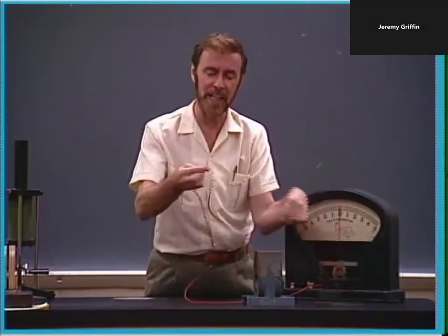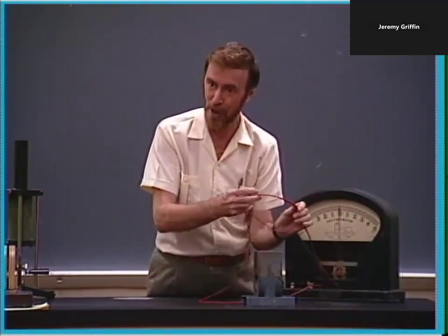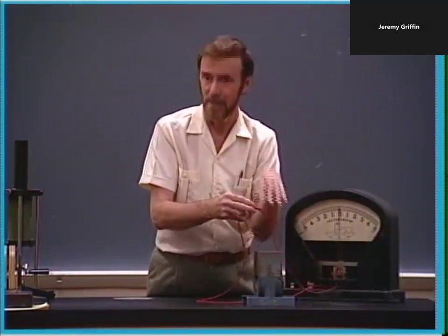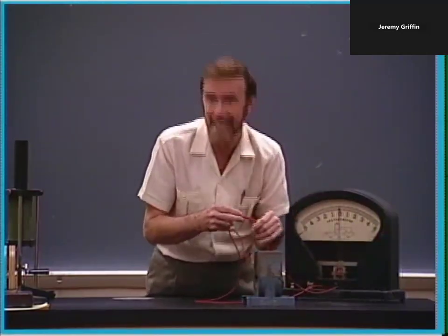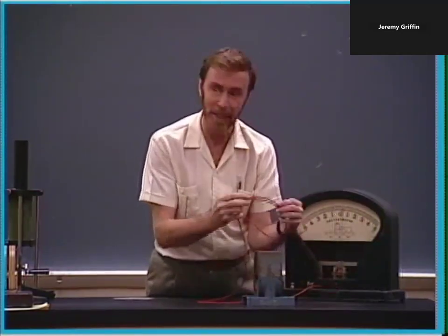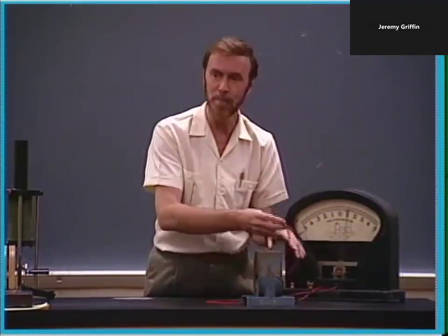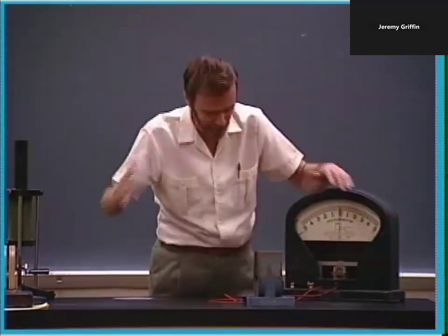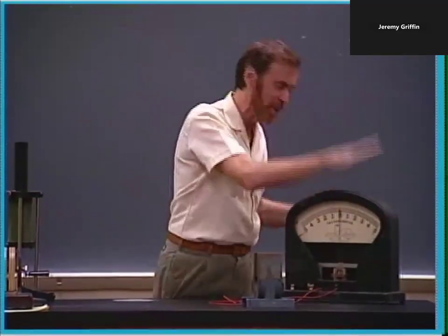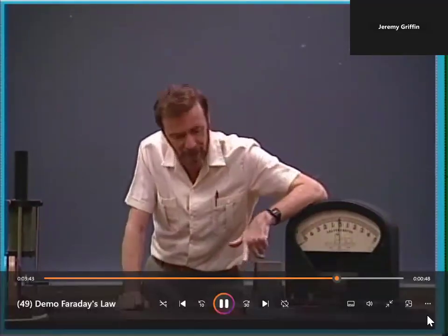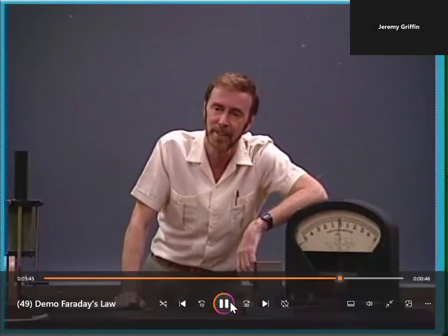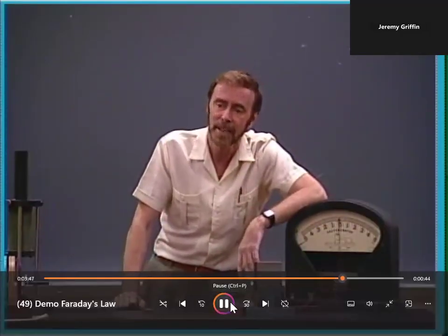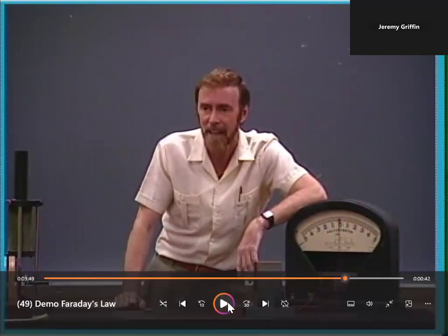Change the magnetic field in two loops of that closed copper wire, two loops of that circuit, and guess what you get then? Twice as much voltage. Three loops, da. Well, that's the rule. All you got to do is change the magnetic field intensity and you will induce a voltage, which will produce a current if you're talking about a conductor. Ain't that neat? That is really, really nice. And so then they started generating electricity.